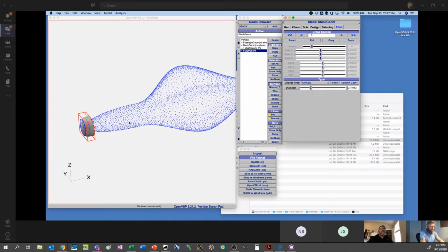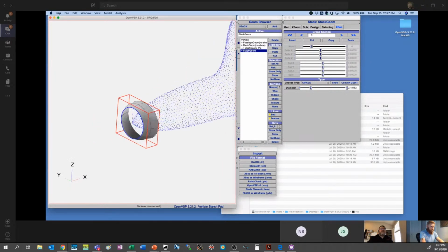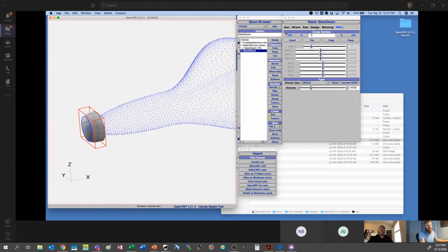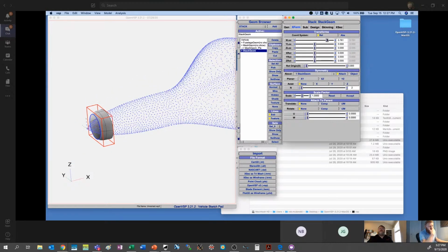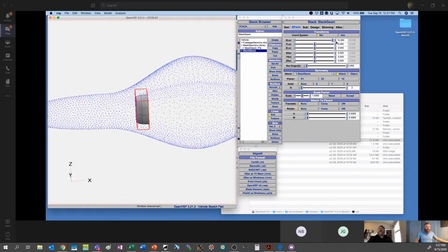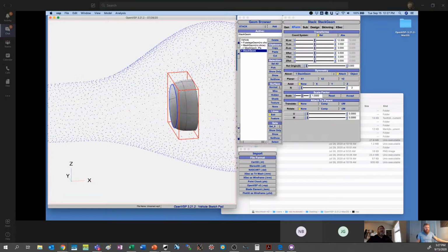So here we have a stack that's just 2 cross sections, and I want to match it to somewhere down here, somewhere down the body. So we're going to match it at 12. We're going to try and match whatever this section is here at 12.